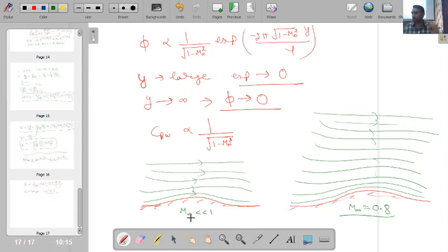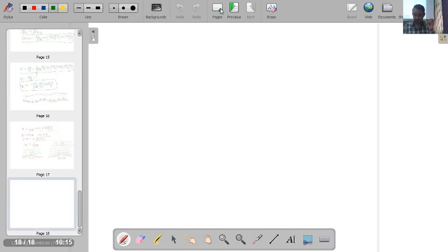So up to more portion we will be feeling the influence of this. Okay. Now another one final thing I want to just conclude. So we have seen this rule that Cp is equal to Cp naught by square root of 1 minus M infinity square. So this was our Prandtl-Glauert rule.